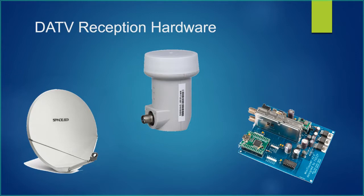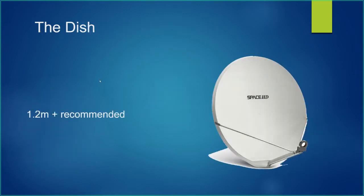For the hardware on reception, you basically use a dish. You also require an LNB, and then the difference is you need a specific tuner to be able to receive them. Now, for the dish side, the difference between the wideband and the narrowband is you actually want a bigger dish. The documentation or the wikis around the internet suggest that you need to have at least a 90 centimeter dish to be able to receive the ATV. My own experience is that a 1.2 meter dish is at least what you'll need to be able to receive the DATV side.